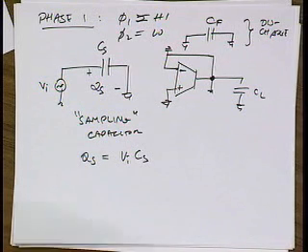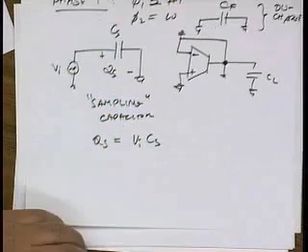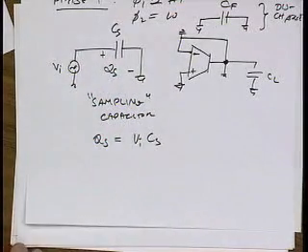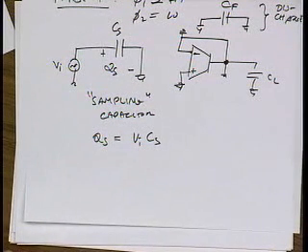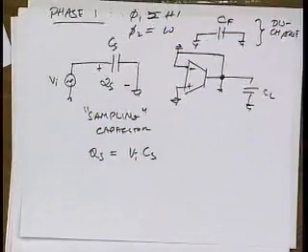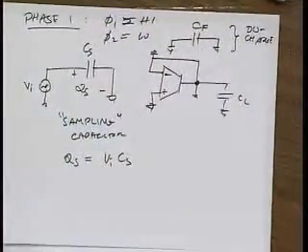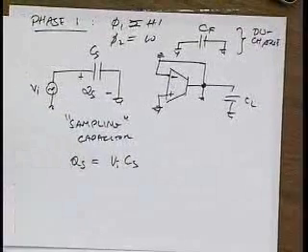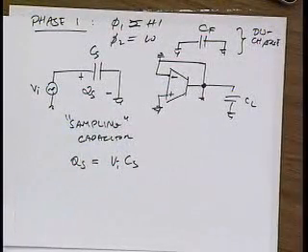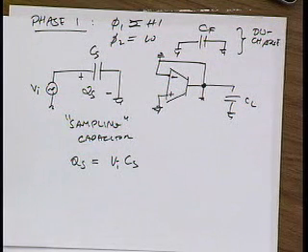Well, let's say there are no parasitic capacitances. What? Yeah, you're close, right? What value do you expect to get? You get what? Okay, it's temperature dependent. That's right. But just give me a number, right? KT? 4 KT? Well, first of all, it's going to be a voltage, right? So 4 KT times what? Four KT times the capacitance? That doesn't give me a voltage. Parasitic resistance of the capacitance.